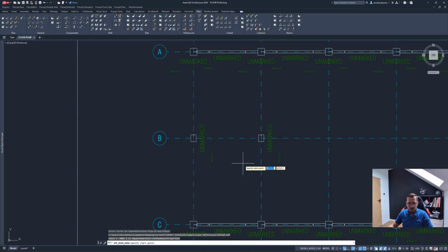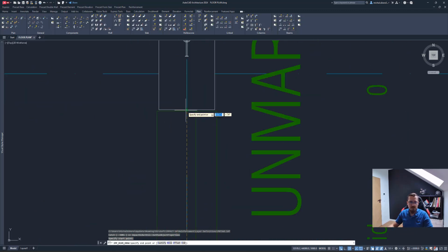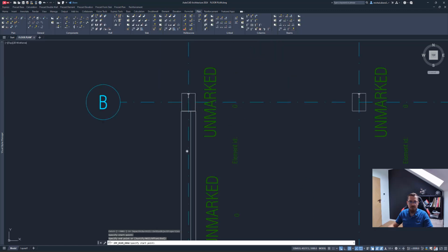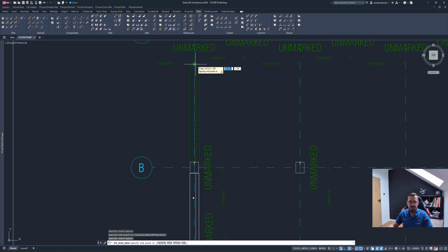Now, one thing that's important is the direction in which we draw the element. I want to go from bottom to top, so my ledge will be on the right side, which you will see right now. And the offset is applied. I can see that, which is good. Yep, that's good. Same thing here. Let's apply that.